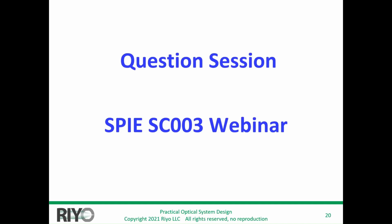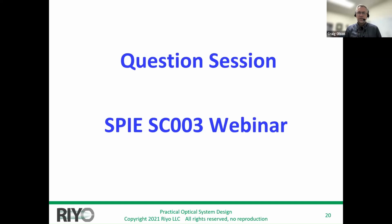What types of optical materials does the course consider? There's a whole slew of discussion on standard optical glass, Schott, O'Hara, things like that. So we spend a great deal of time going over glass maps, what the specific nature of visible glass is. There's also quite a bit of information on infrared materials, silicon, germanium, chalcogenides, things of that sort. So we do actually spend a fair amount of time talking about the materials. I think it's probably close to 15 to 20% of the class.